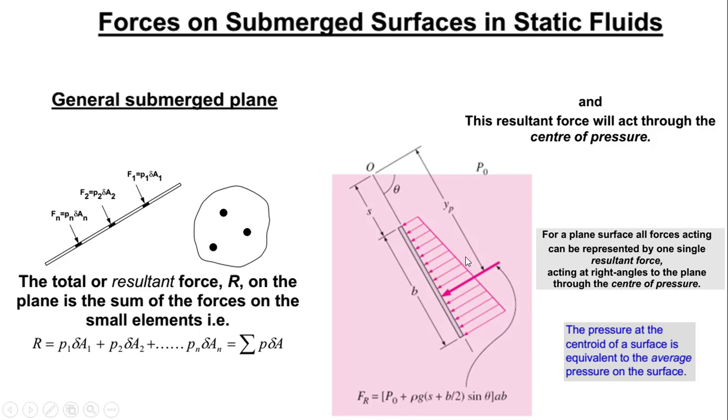This means our center of pressure is going to be located towards the point near the bottom. It's like being on a seesaw: if you've got higher force on one side, to balance the moments the other side is balanced by the length of the beam. That's why we get higher force at the bottom, due to the fact that pressure increases with depth. We know that force is equal to pressure times area, so if we've got higher pressure here, we've also got higher force.